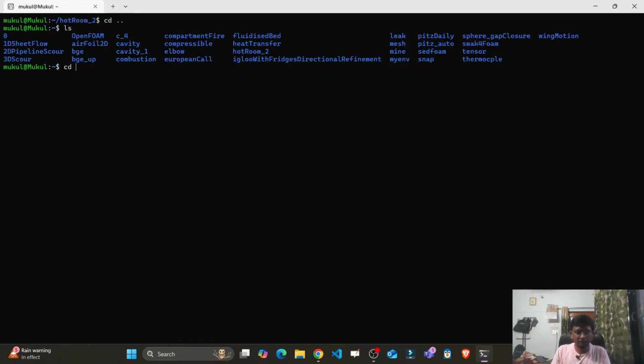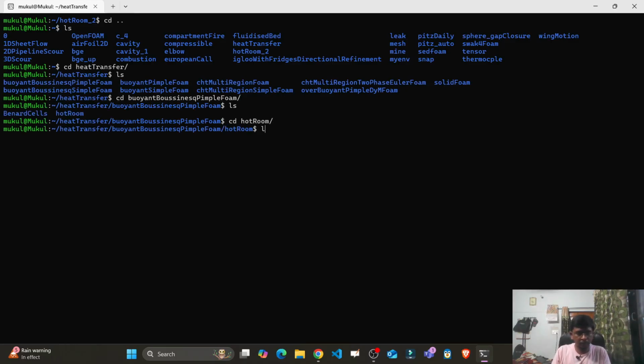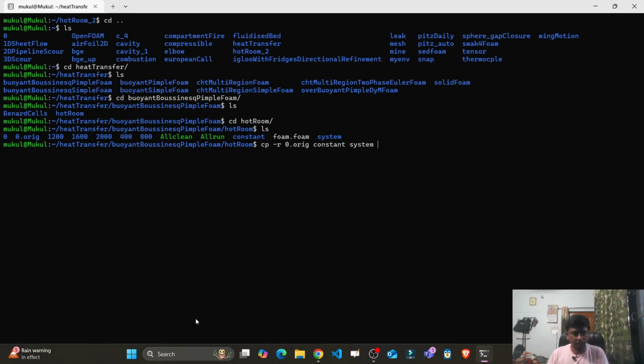Clear. Go back. Go to the tutorials, heatTransfer, buoyantSimpleFoam. Go inside hotRoom. All right, so what I will do, I will just copy some files. I'll just copy, cp -r, 0.orig, constant, system to my directory.